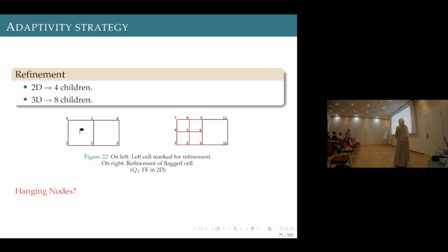It's a different space, right? I'm not sure. I think you have the same basis functions, right? The basis functions inside the element are the same. You are refining, and the space is still bilinear on each element. Let's say you're using Q1, bilinear on each element, and you just add an equation that imposes the continuity at the hanging nodes. Okay. Thank you. You're welcome.